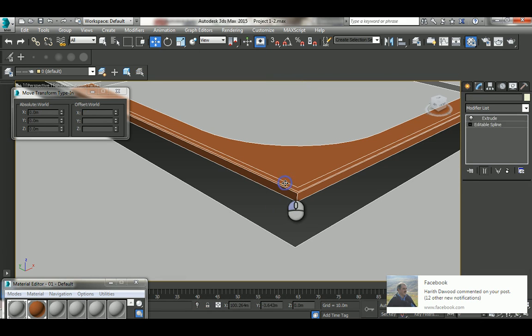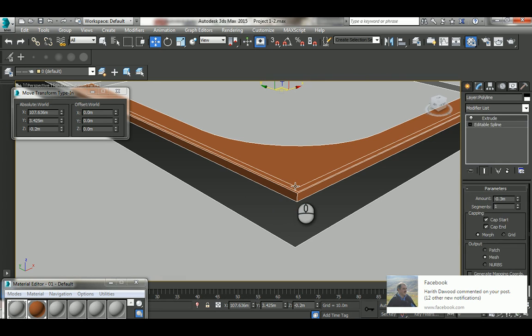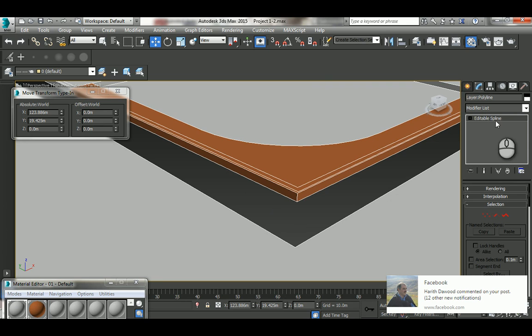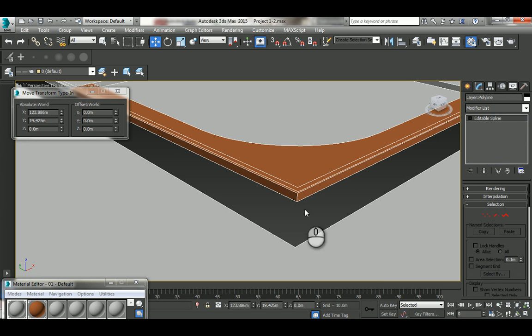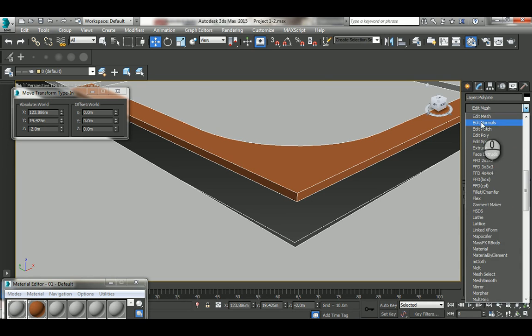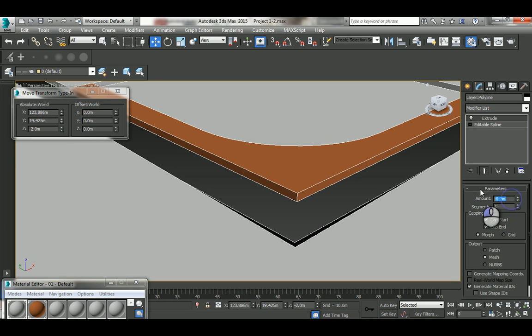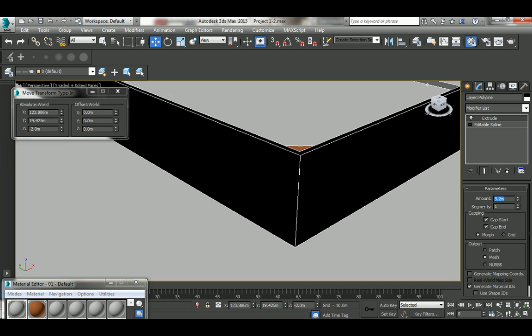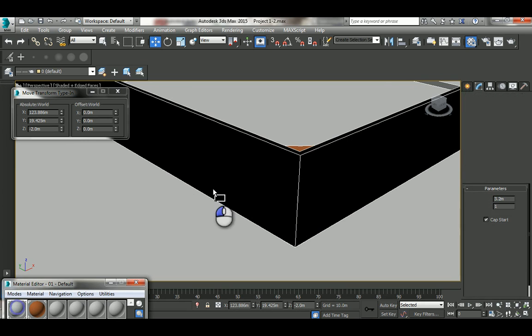The trick that I have: the line that I select shouldn't have any kind of extrude above, so that's the right one, because all the previous clicks that I had were having an extrude above, except this one, and that's a good indication that this is the new one that I just imported from CAD. I'll give it a -2 to the lowest point, and then give it a positive extrude of 3.2 meters to reach the height of 1.2, which is this point that's required from me in AutoCAD.